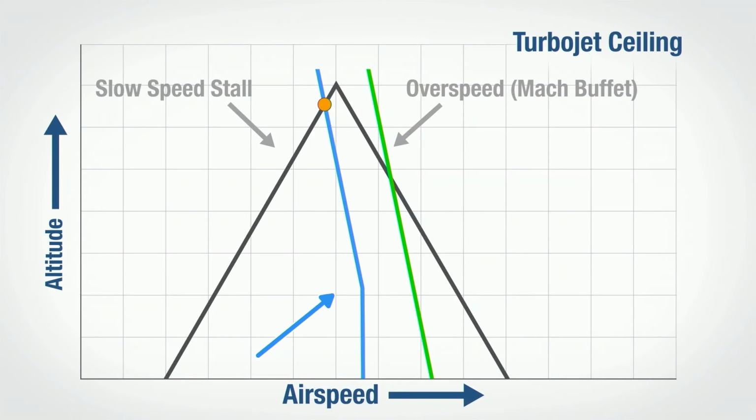Eventually, that engine is going to run out of headroom. And just like a basic jet engine, it's going to start to lose power with altitude too. So if you look at a more modern aircraft, you'll notice essentially its thrust capability is flat, and then it also starts to fall off. But you'll notice here that oftentimes it can only generate enough thrust to get close to overspeed, but in level flight, many airplanes have a difficult time actually getting to overspeed or critical Mach.